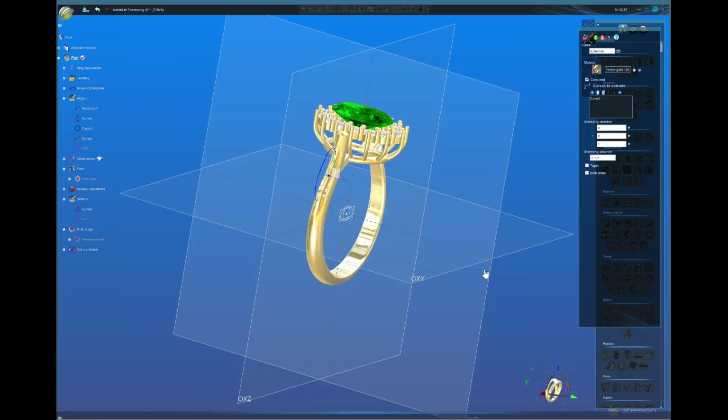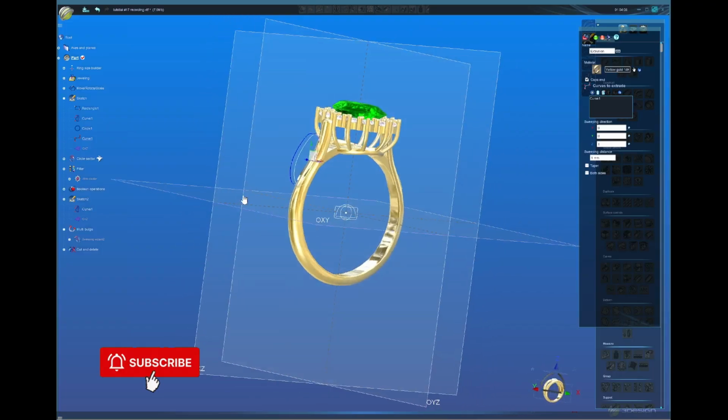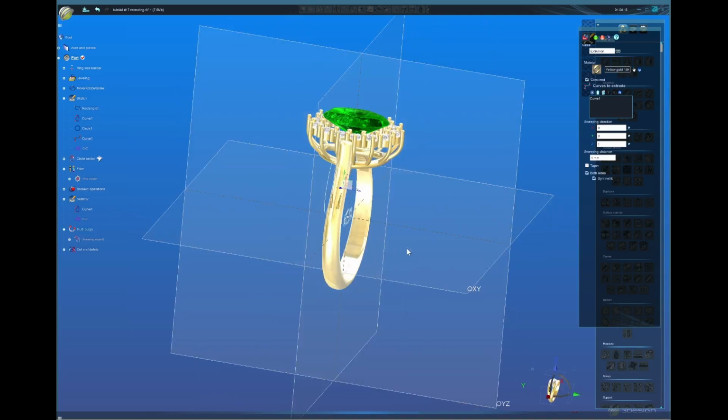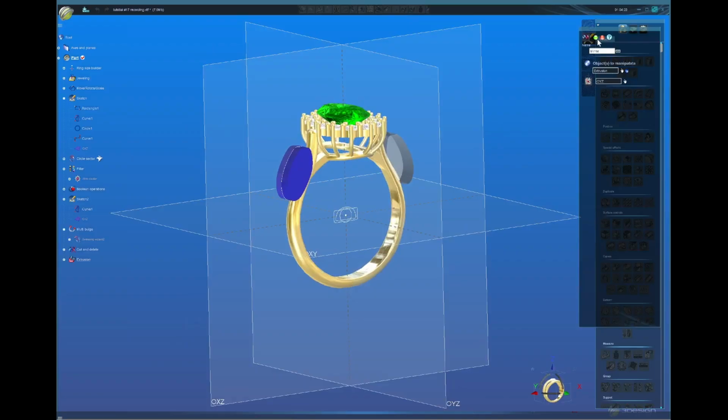You get out. You can do an extrusion here, or you can also get the curve and mirror to the other side and clean up this way. What I'm gonna do, I'm gonna do both sides, click OK, and I'm gonna do the shape to the other side.